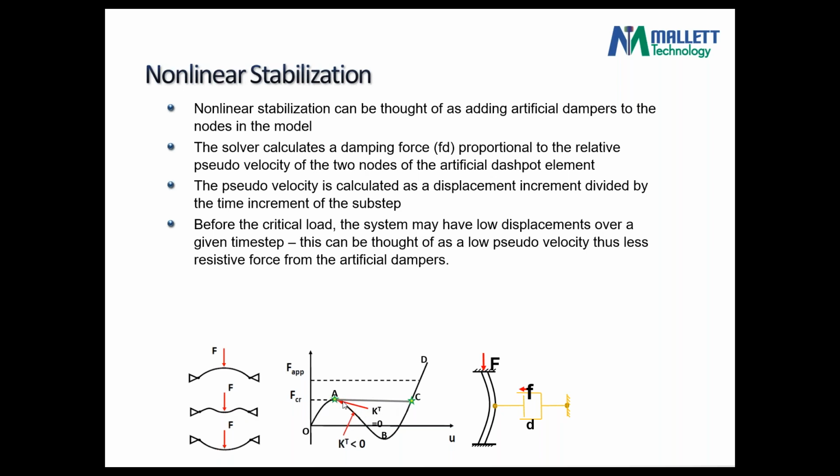So displacement at this location will be very large, okay? Meaning because the structure is unstable. Large displacement will cause large forces, and hence I can apply this artificial damping in a controlled fashion with large quantities if the instability is large, and if it's small, then it will be small. However, one has to be careful how much of it to apply, otherwise you either predict the wrong shape, or it will just stop. You get a solution which is the wrong solution.